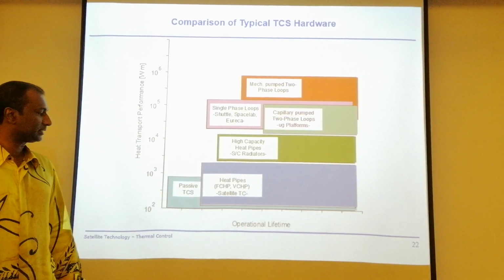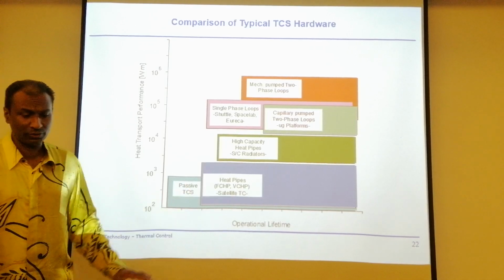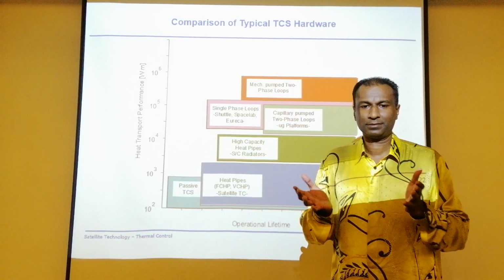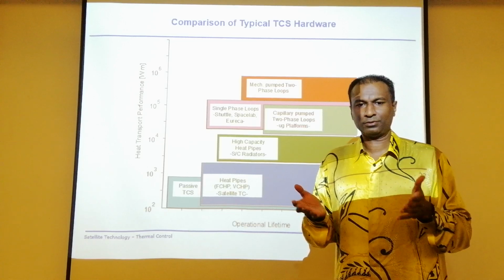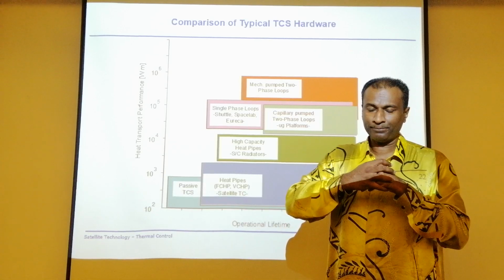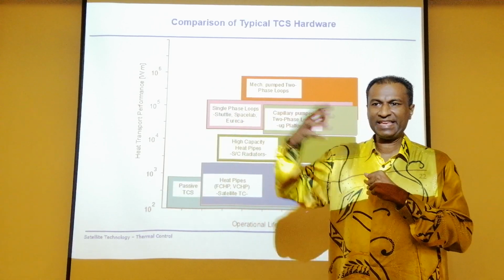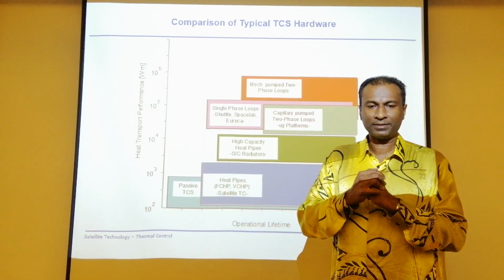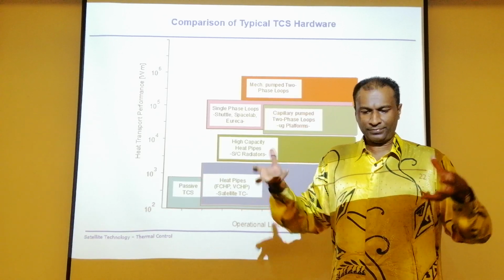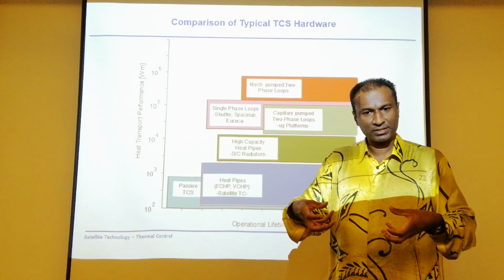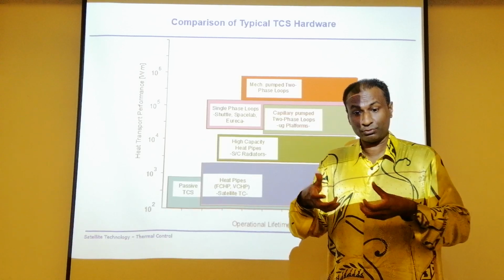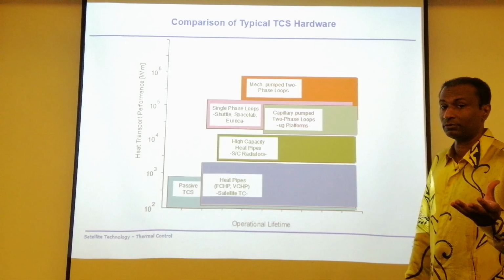A passive type of thermal control system includes not only heat pipes, but also insulations, like blankets. You have the thermal blankets, as we call them. Later we will discuss thermal blankets. Thermal blankets can be used to protect against any radiation or any heat from outside. Imagine if you want to bake something, you have that aluminium foil, you have the food inside, and then you wrap it up. That is going to contain a lot of heat inside. So that is also a passive thermal control method.